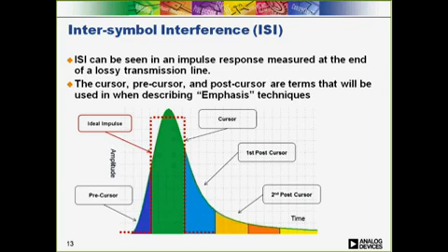De-emphasis subtracts the energy in the pre- and postcursors, so only the energy at the cursor remains, theoretically, after the signal travels through the channel. We will discuss the different emphasis techniques in later slides.